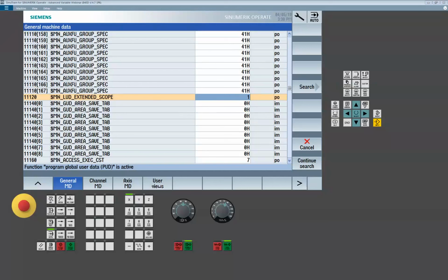This way, if somebody resets the program in the middle of the subprogram executing and kills it while you're in that state, well, guess what? It's staying in that state. So if you just switched a guy from inch to metric, and in the middle of the routine he hit reset, now the machine's sitting at metric, and he may not realize that. That could be bad. So just be careful with some of that stuff.